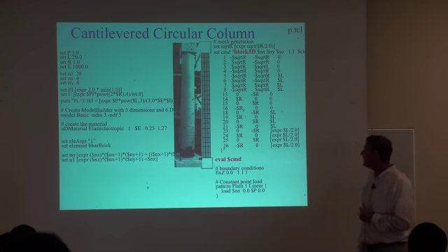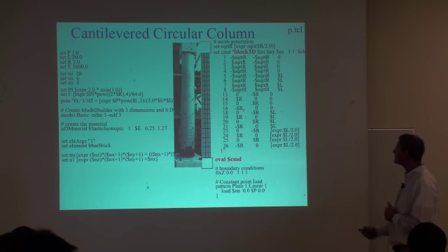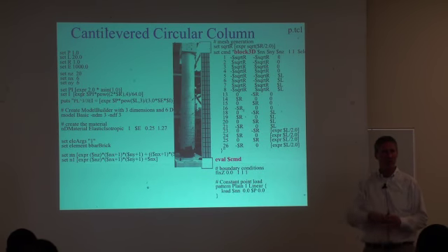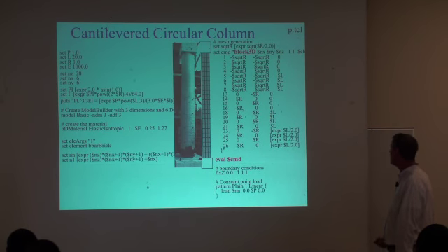Lastly, a 3-dimensional cantilever column. So I'm just going to do an elastic model. We need the brick element. Instead of the block 2D command, I'm going to use the block 3D command. We have to specify, if it's rectangular, it can be 4 corners. In this case, we're specifying 8 at every point, roughly specifying a circle. This is creating a circular mesh as opposed to a rectangular mesh. That's what these things are here. Again, we issue this value command to evaluate this.